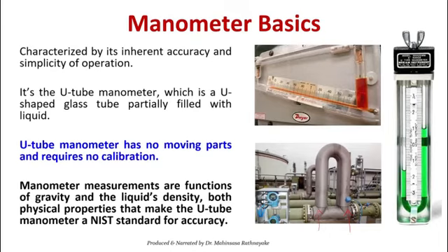Then from the basics, pressure is equal to h rho g. So in that case, you need the conversion of the pressure to height. You need the standard properties of the liquids. Then you can use the accurate values from the standard values. In developed cases like this picture it would be okay, but if you want to introduce a very simple manometer type pressure gauge, then you need these property values to convert the values and find out the exact pressure. That makes some difficulty because you have to do some calculation, or you have to scale the indicator based on certain values. If those values are not accurate, they will affect the accuracy of the instrument, right?